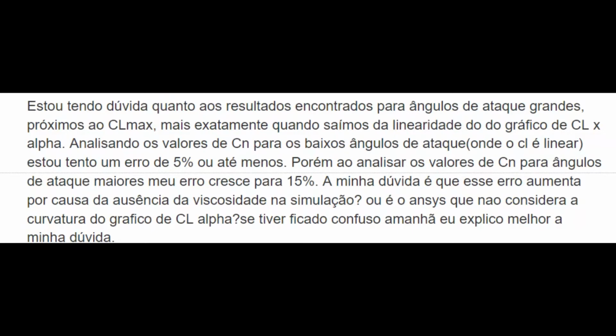And also another reason is that inside K epsilon K omega model, we have so-called characteristic length, which is calculated as a distance from the wall to the body, but not always this distance can be calculated. For example, when the boundary layer is separating, it is growing in a different way than going together with the wall.